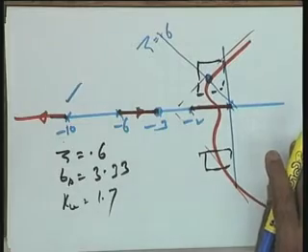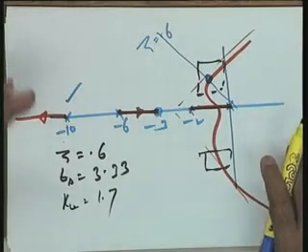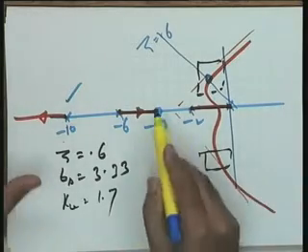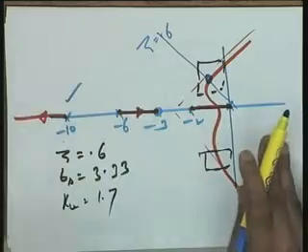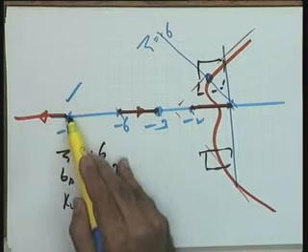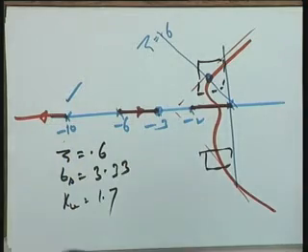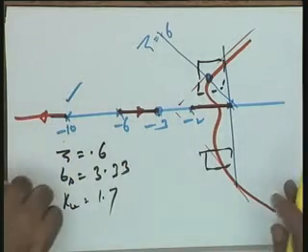This I assure you that systematic trial and error procedure is available by which this pole and zero both can be tried. How many total parameters are there? Please see, the total parameters are the zero location, the pole location and the amplifier gain. I still assume that the amplifier gain is available for design.